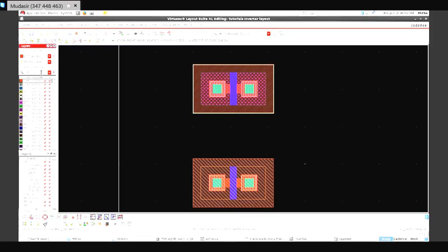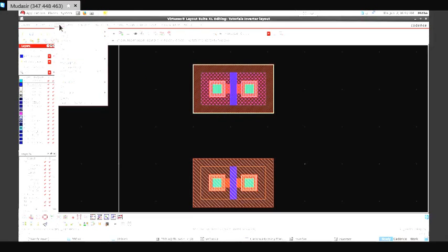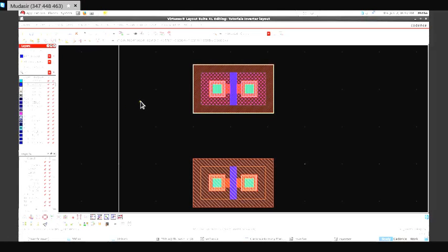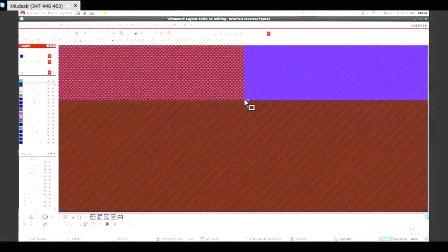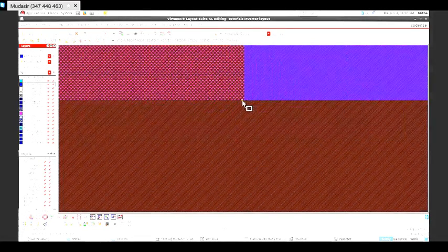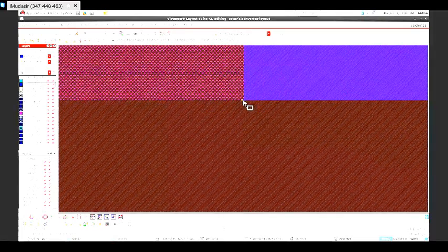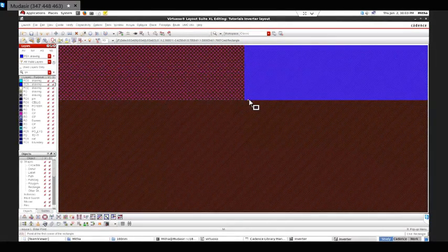The gate I had connected with the basic poly layer, so it's PO1. Okay, so again there are many ways to connect here. One is I'll use this drawing, I'll go create, I'll just press R for rectangle. Okay, so I can just zoom in. See, I had to go exactly from here. Again, if you see here, it's not allowing me to start from this one because of that step size. This will give me DRC errors.